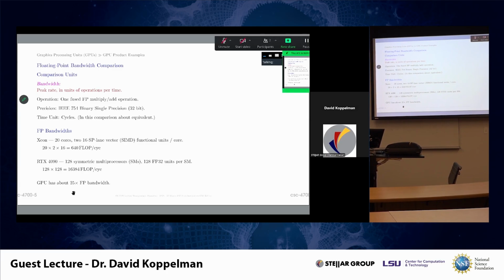Okay, another thing that CPUs do that GPUs don't is with the number of instructions that can execute at a time. You may have heard the term superscalar. In a typical CPU, like an Intel CPU, peak would be around 8 instructions at a time. Now, it's more complicated, they're micro-ops, but roughly 8 instructions at a time peak.